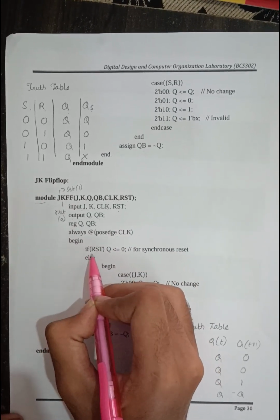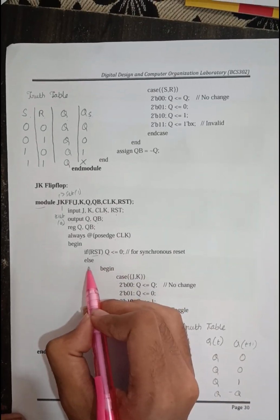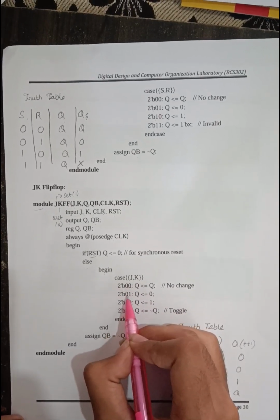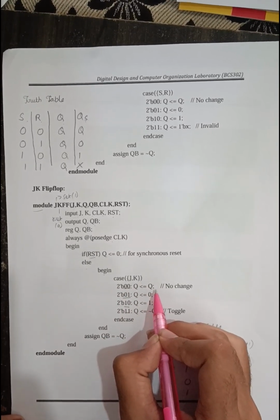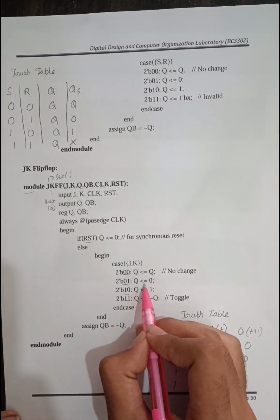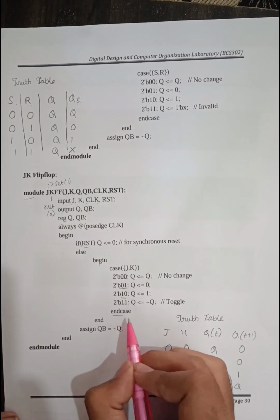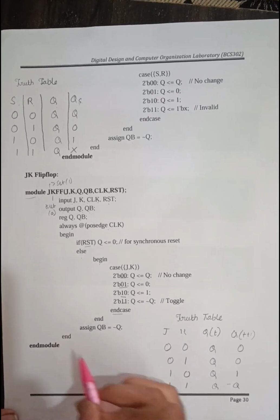Begin with if RST, reset value of Q less than or equal to 0, or else begin with case of JK. 2'b of these are the decimal values. 2'b of 00, Q less than or equal to Q. 2'b of 01, Q less than or equal to 0, and so on. It ends with end case and end, and then assign QB equals inverse of Q and end module.